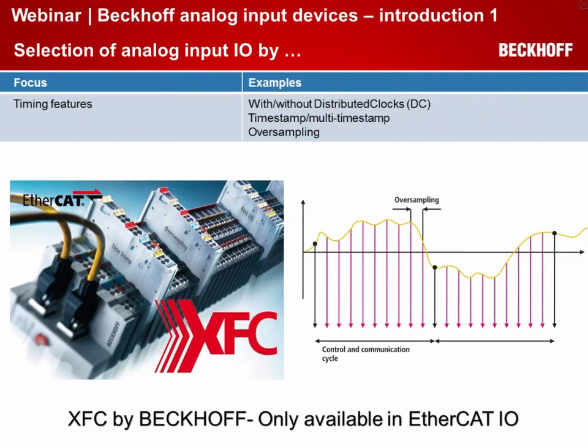Timing features can also be a requirement for an analog input. Beckhoff has the family of XFC terminals, extreme fast control. That means these are analog devices, terminals, that are specially designed for very fast sampling and very fast reaction. They're always working with distributed clock as time base for simultaneous operation, and some of them are working with a timestamp and others are working with an oversampling, a very important feature, so I will explain it here on the right side.